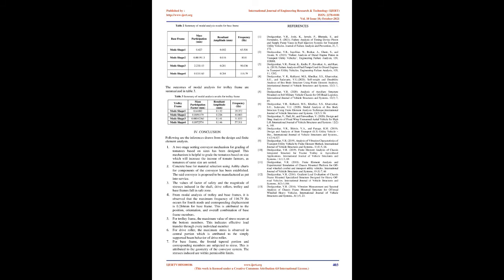of torque and uniformly distributed force on it. However, corresponding factor of safety value is 2.49 that signifies safety of shaft design. The stress value observed in trolley frame is 125 MPa and corresponding factor of safety value is 2.79. The stress value is far below the permissible stress value of 350 MPa. Maximum displacement is also observed in trolley frame. Additional stiffener plates are suggested to be welded to enhance the stiffness at the central portion.